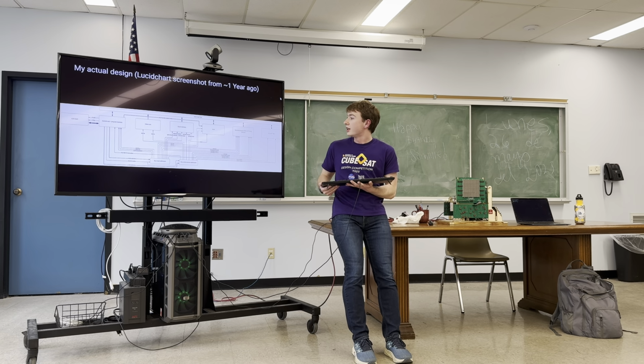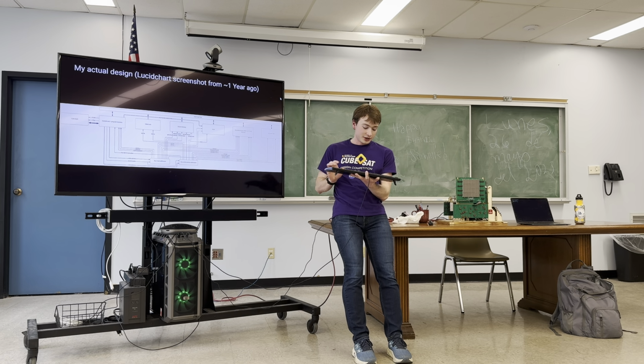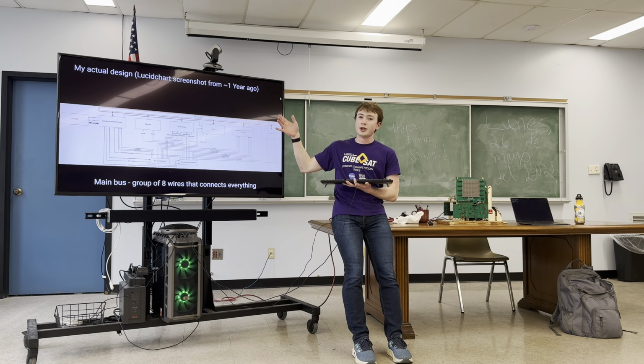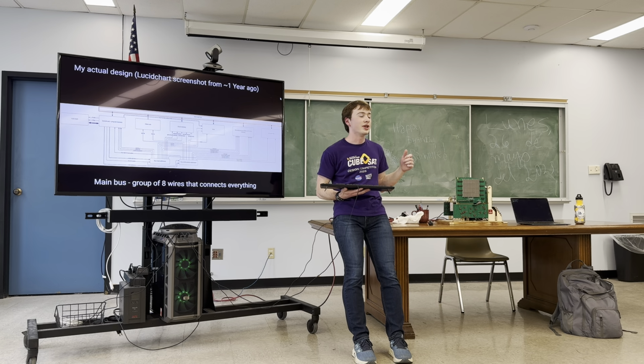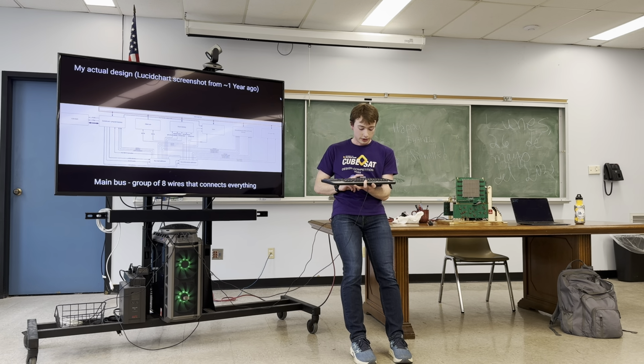Alright, now I'm going to talk more about my actual design instead of random diagrams. This is another bus. It's 8 wires, along the bottom horizontal board, and it connects almost everything. Pretty much everything that writes to it are 8-bit data latches. Most of the outputs are disabled so they don't conflict with each other.